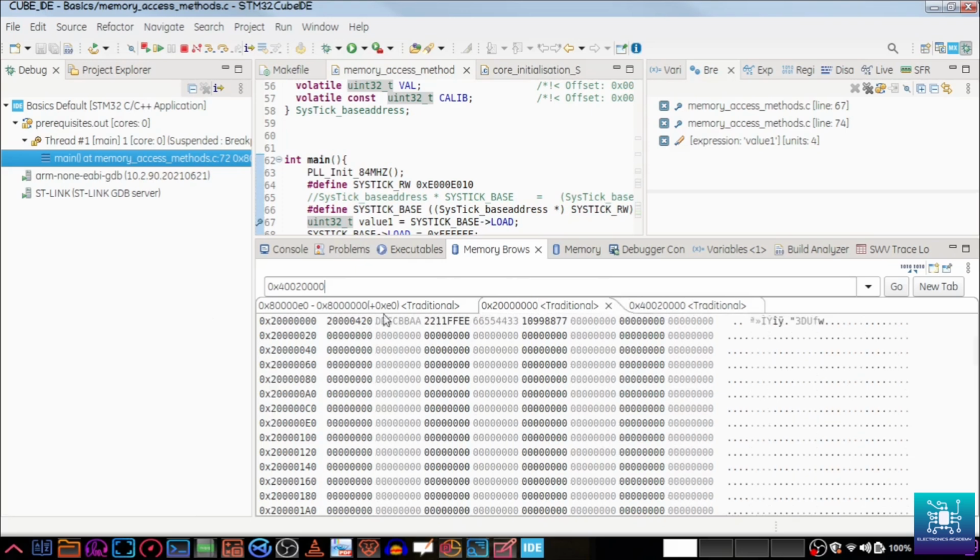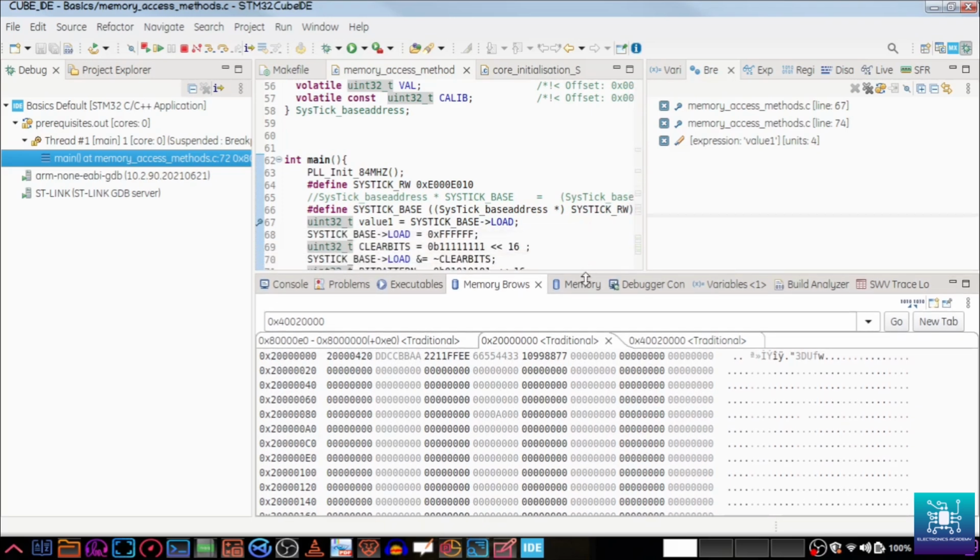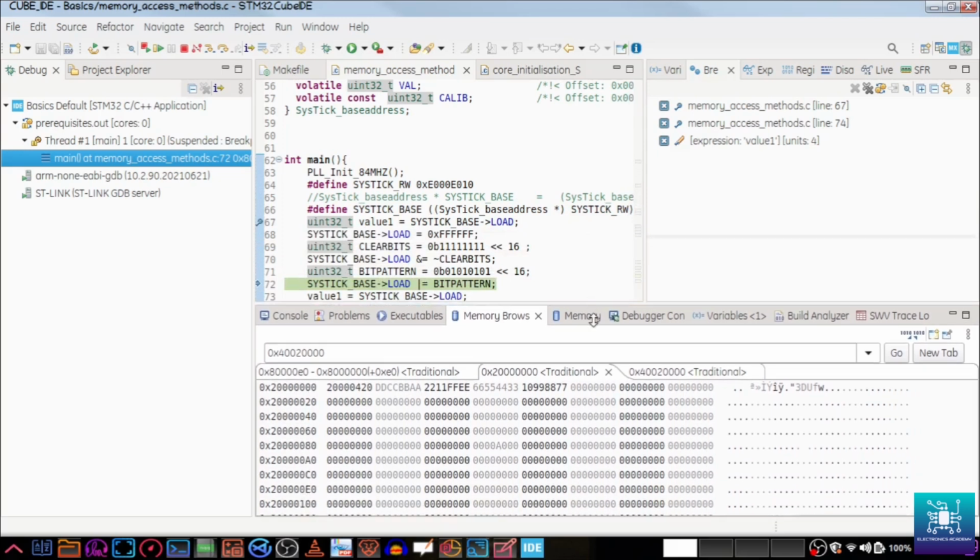And it is possible also to alter the values when you come to RAM. Suppose you come here, you can actually alter the value here. So you can just alter the value like this on the fly, and the value is actually going to be altered in the memory. Okay, so that is also something that you can do. If you press enter, this particular value gets altered. So that is also going to be necessary in certain cases where you check something. Okay, and you want to directly access that particular memory region and make some changes to it without writing code, you can do that.